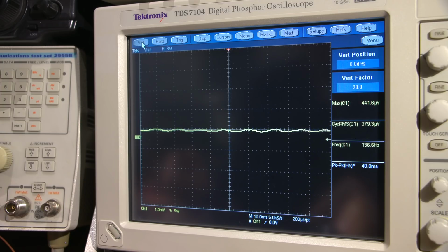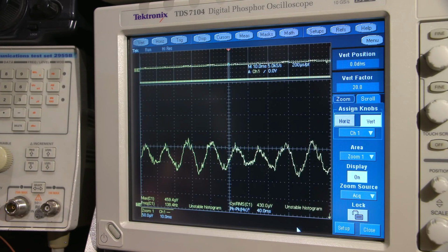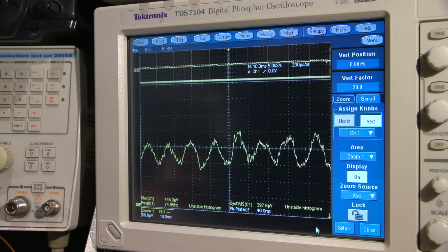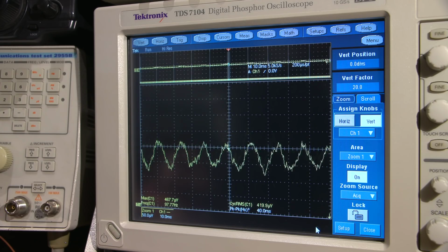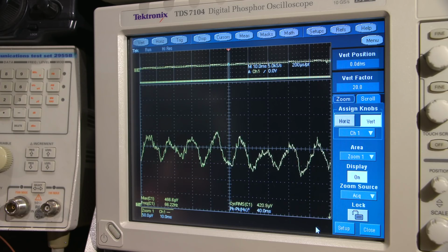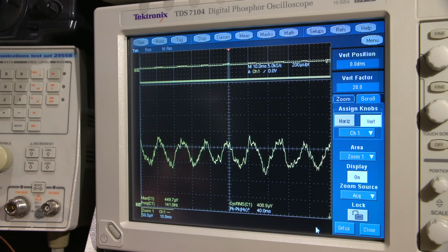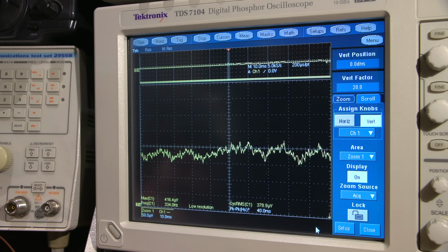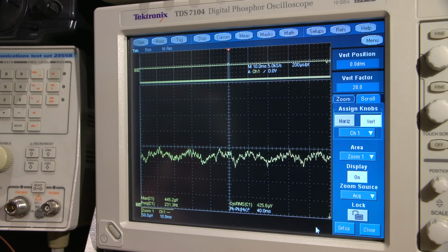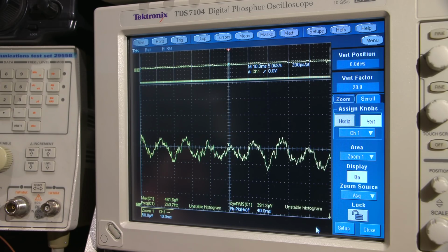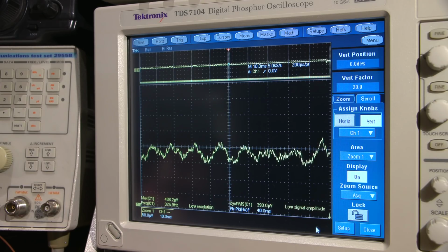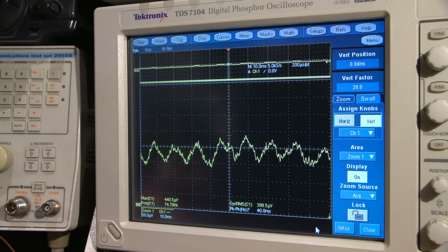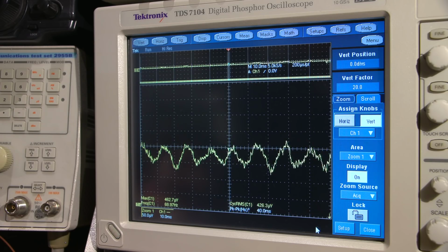So I'm just going to click on the vertical zoom, and I can see the signal in there. As you can see, really, it's just a bunch of noise and gibberish. But I know it's the signal because I'm going to use my signal generator as the reference. So I'll turn the amplitude down on the signal generator and watch what happens to the signal. See, it goes away. So I know that I am looking at some signal. I'll turn this up just until I get that last LED lit again. That's about comfortable. So I know that that is the amplitude. There's just a lot of noise mixed with it.